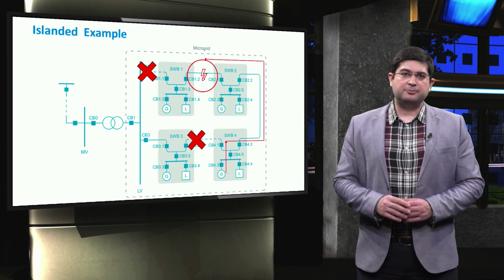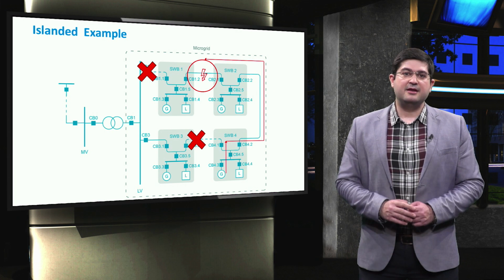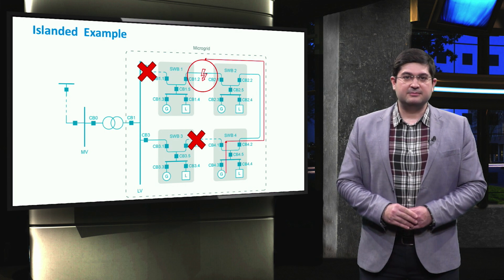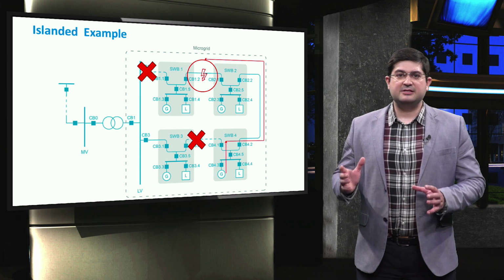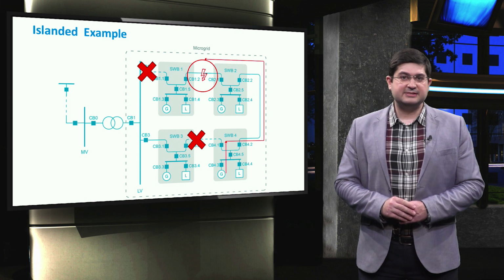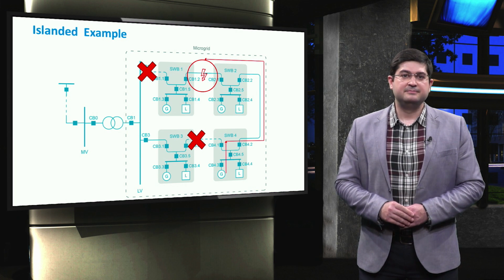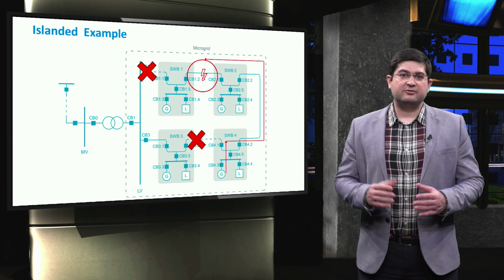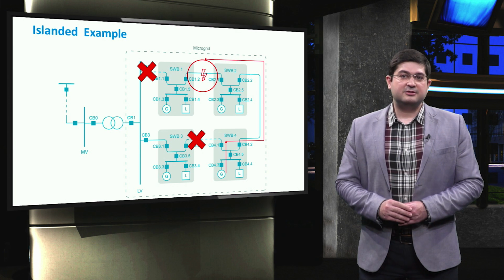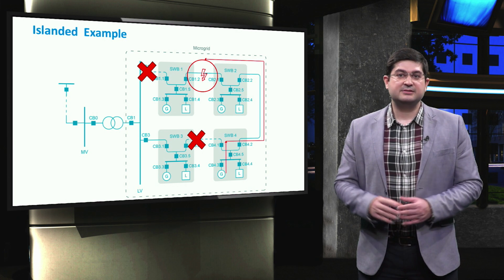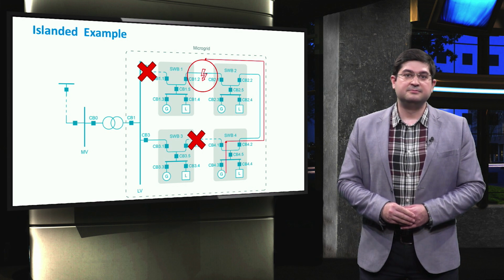The implementation of the protection schemes in microgrids is typically more complicated than a normal radial distribution feeder. This is mainly due to the fact that many factors which have serious impacts on the performance of the protection scheme are more frequently changing in the context of a microgrid. For instance, the configuration of the microgrids largely changes not only during the normal operating conditions, but also during the transfers of their operating modes, meaning grid-connected or islanded modes.